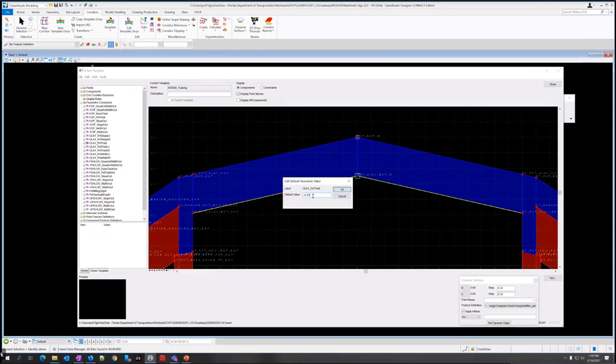We want to change the default value from -0.25 to -2/12. So if you're trying to do inches, you can just do this, and if you hit tab, it'll do the math for you. And then -0.17 is what it shows.